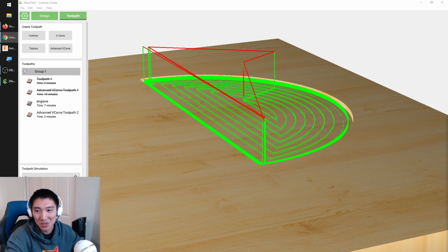What is the best place to start with 3D carving? That's a pretty broad question. It could just be like what software or what to carve, or how to carve. But I would say start with a ball end mill. Start with a really basic program, because whichever software solution you choose, Meshcam, Fusion, Create Pro, Vectric, they're all going to have a bit of a learning curve.